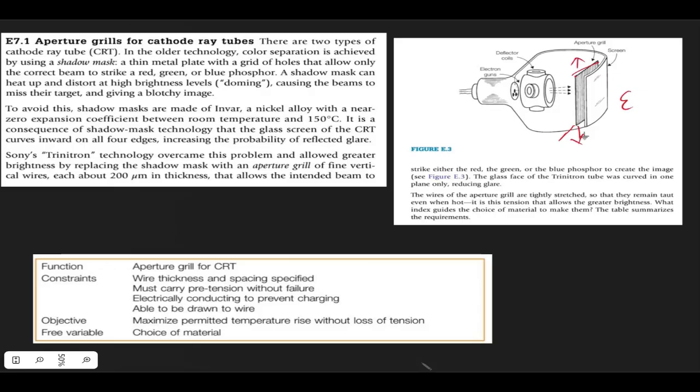An electron beam passes through this material and it heats up to a particular point. You don't want another expansion based on the heat, because when you heat a material, it expands, and you don't want an extra extension since you've already extended it to a pre-stressed length.